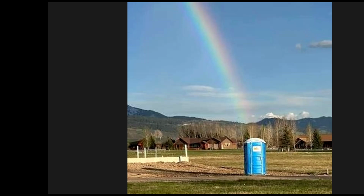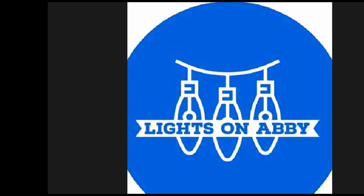It's an FPP command called all lights off. Is that the one you use, David? Yeah, that's what I'm referring to. So I would throw the command between sequences to clear up all pixels that were going bad. And I ended up having to replace 5,000 pixels because they were bad. Once I did that, I haven't had that issue these last 2 or 3 years. But I think there was a universal problem with pixels in 2019 and 2020 across the hobby, because of the chip shortage and everything else going on in the world.